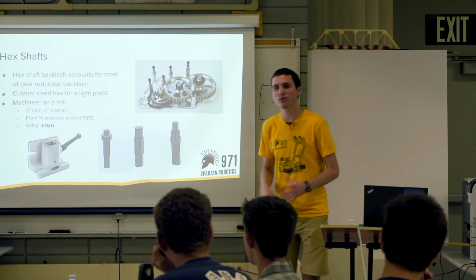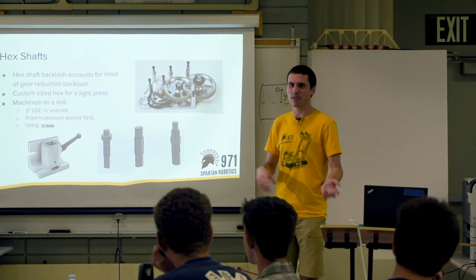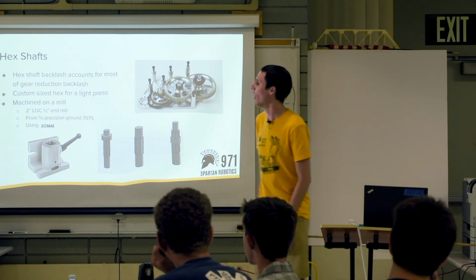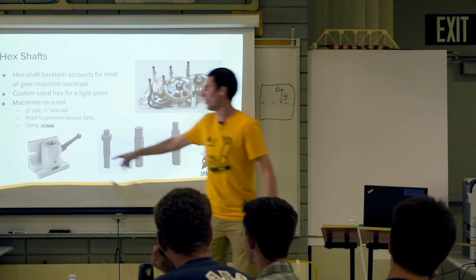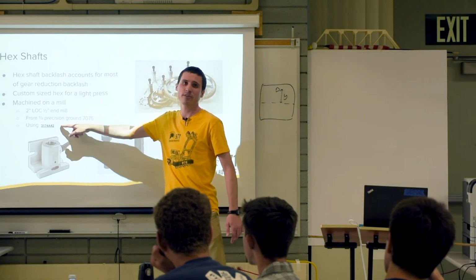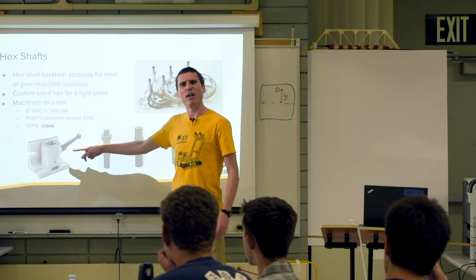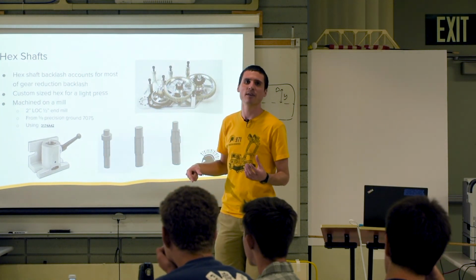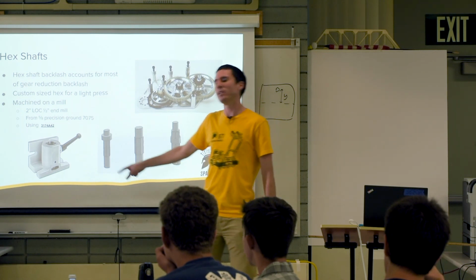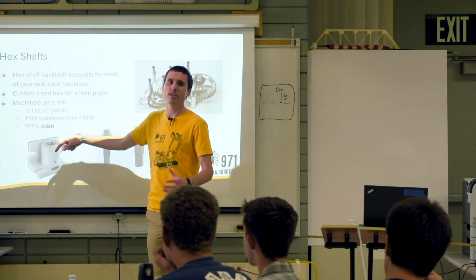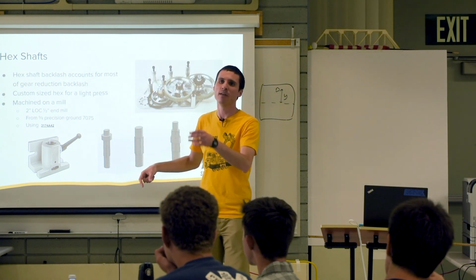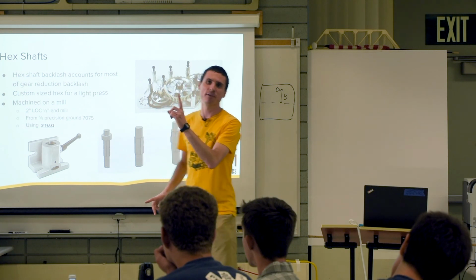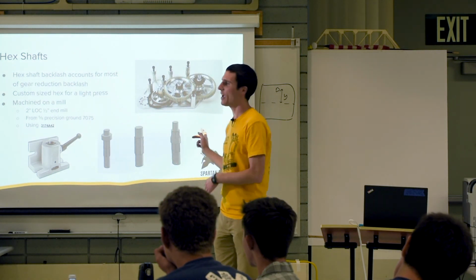And then from a design perspective, the way to make this work out is to make sure you design it with how you're going to machine it in mind. So what we do is we use this vertical collet block. This is a part number off McMaster, if you want. You guys know the 5C collet system on the lathe, are you familiar with that? What this does is take one of those collets and allow you to hold something vertically on the mill. It's machined so that it's going to hold it straight vertically, well enough that you could use it for a shaft.